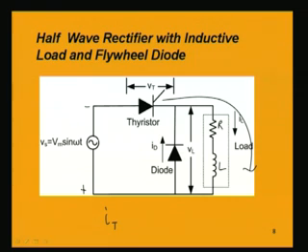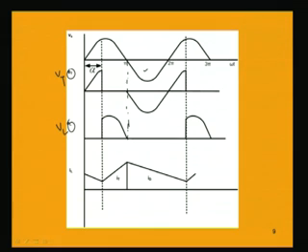supply, because if we apply the voltage law here, then the voltage across this is equal to the voltage across this, because the diode drop is 0. So, we get the voltage across the thyristor as the supply voltage till it again starts conducting, then again it will be 0. The voltage across the load will be 0 till the thyristor fires, then it will be equal to the supply voltage.